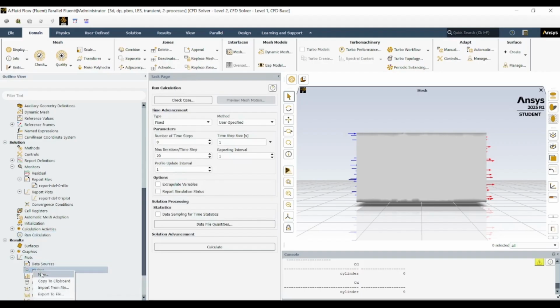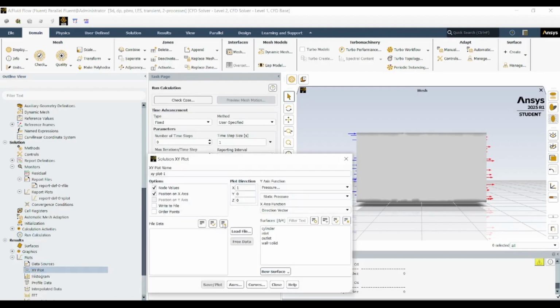You can also visualize vorticity and streamline patterns for a more advanced flow understanding. In Fluent's Contours menu, choose Vorticity Magnitude. Red and blue zones indicate counter-rotating vortices behind the cylinder. These contours change dynamically in transient simulations, providing an intuitive visual of the von Karman vortex street.